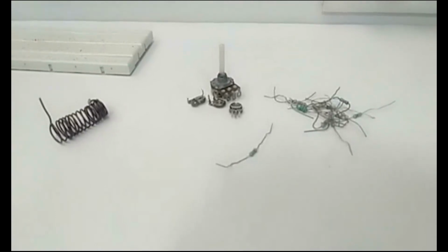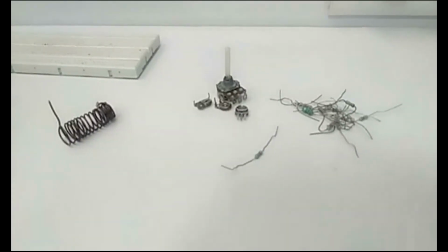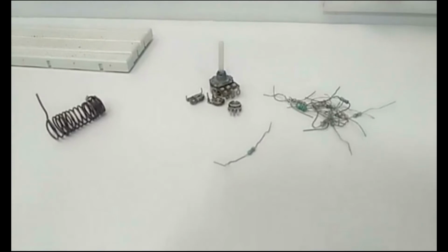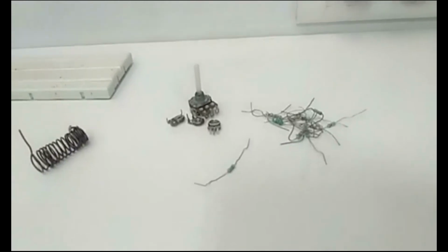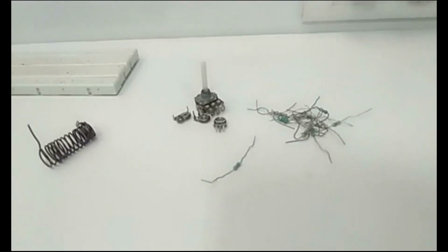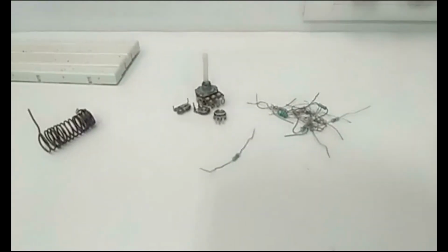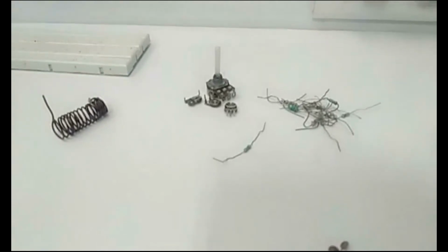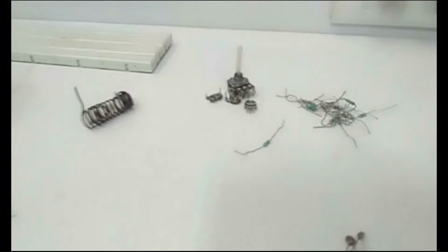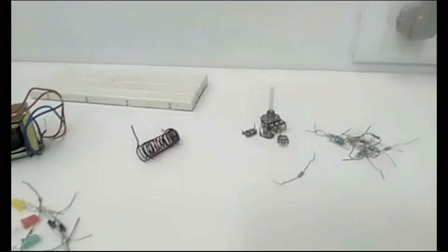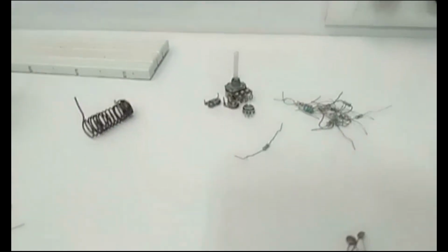The color may not be clear to you, so I'll show you later through my screen sharing that the carbon resistors have color codes. Through color codes, we can estimate the resistance of that particular resistor. It is a very helpful technique for performing day-to-day experiments. Otherwise, you would have to measure all the resistors one by one, which would be very time-consuming. I think all of you are familiar with the color code.